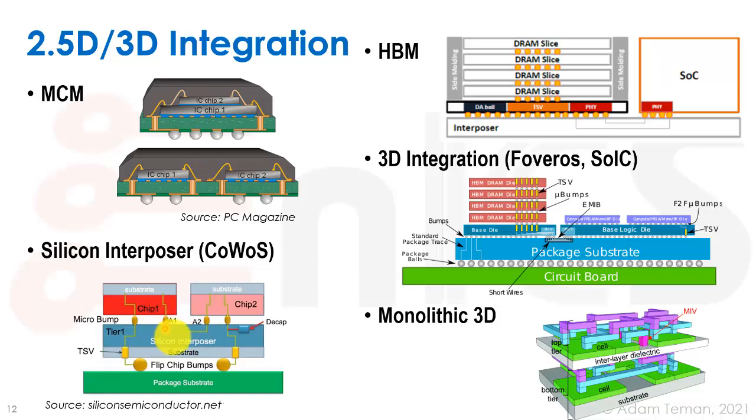They're going to be connected in a VLSI layer on the silicon interposer, and another one's going to be connected to the package through silicon via. So each of the times that we actually punch through the substrate of the silicon, that's going to be using a TSV, which is the answer to the question that I asked.